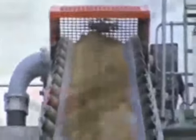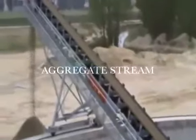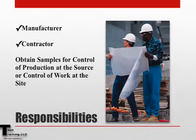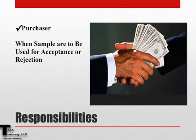The responsibility for obtaining the sample will depend upon the reason for which the sample is being obtained. As an example, the manufacturer and contractor are responsible when the sample is being obtained for control of production at the source or control of work at the site. But it is the purchaser who is responsible when samples are being obtained to be used for acceptance or rejection as a potential source.